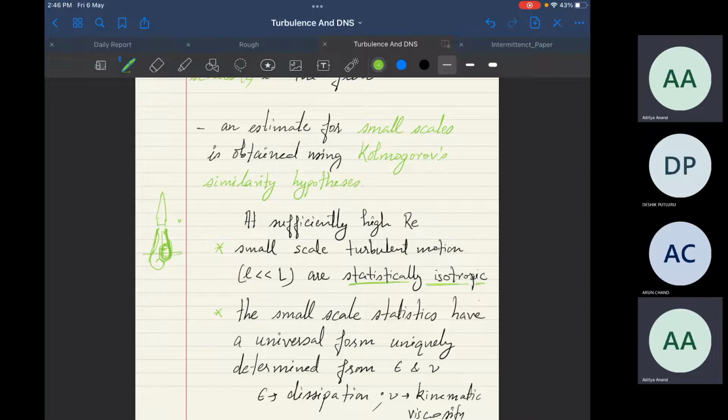Now, if you take a section here and look at them planarly, they'll have some toroidal kind of shape. It might not be a full toroid, but it will have some shape. The shape of this large eddying motion would be such that it will convect downwards, so it has a directional preference.